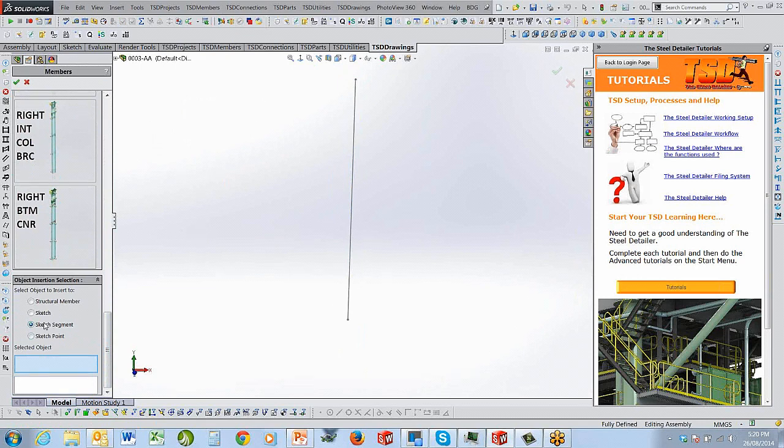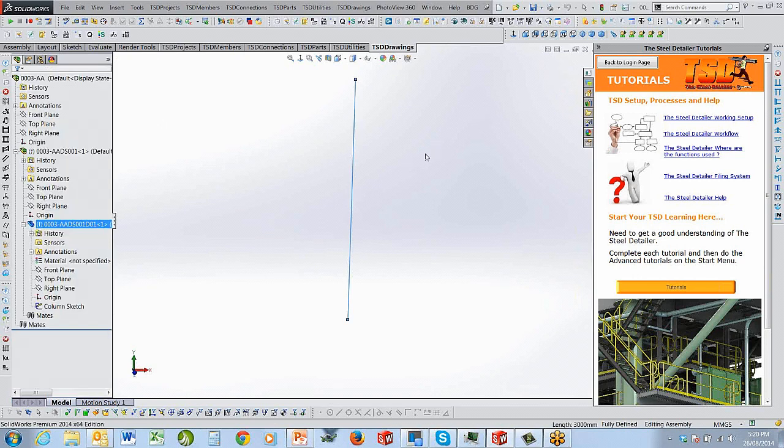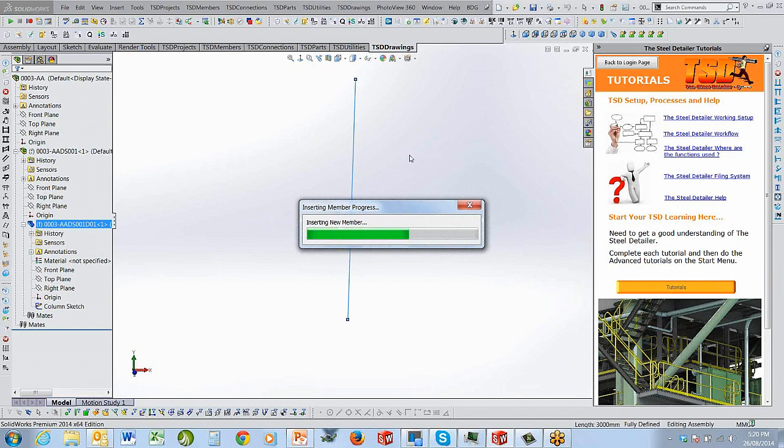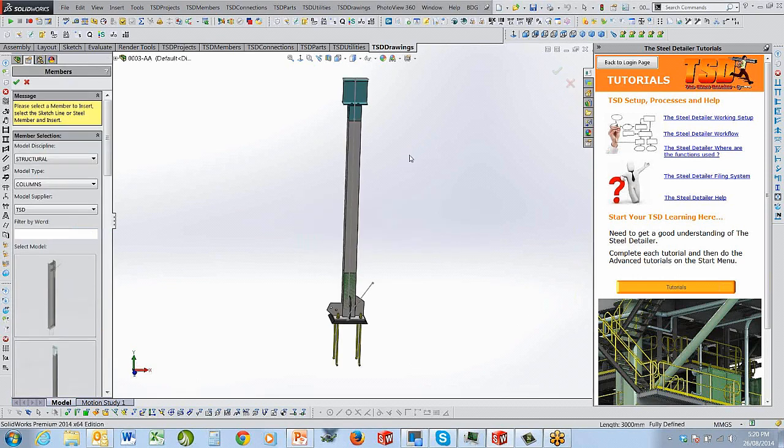So basically I'm going, I want to select a sketch segment. These are the two sketch selections for the driving sketch segments that I want to attach my welded member sketch to. And then I just pick one. I don't need to pick the second one. It's an option. In this case, the column's only just the one.